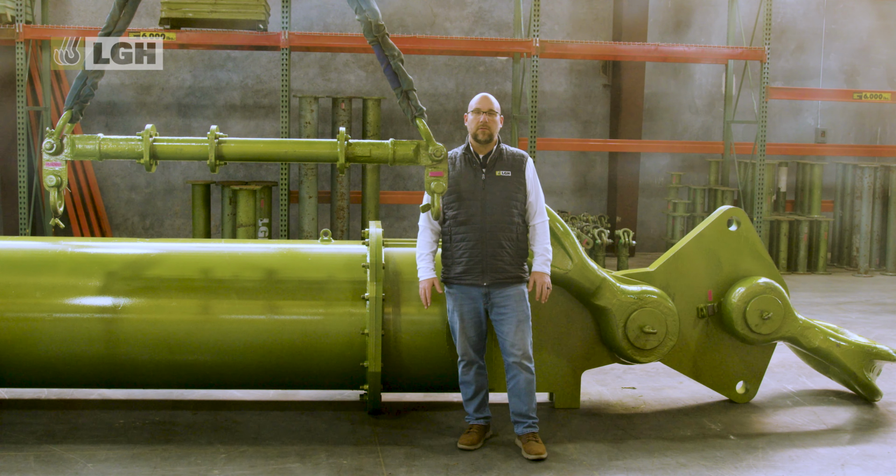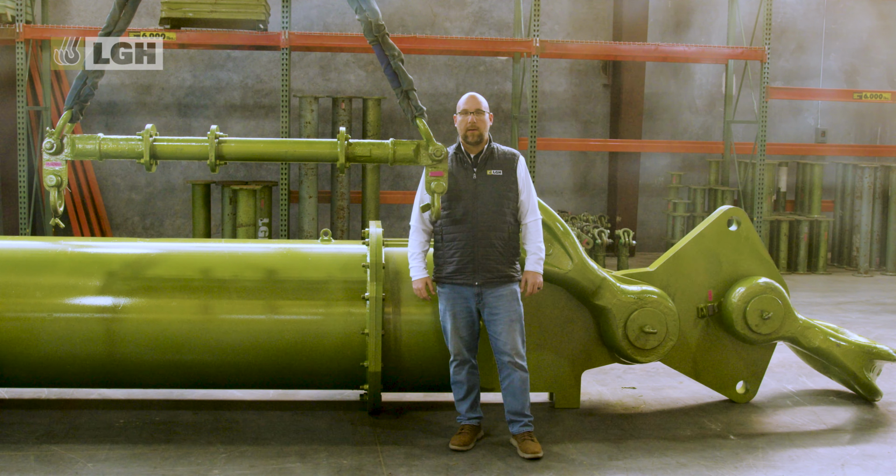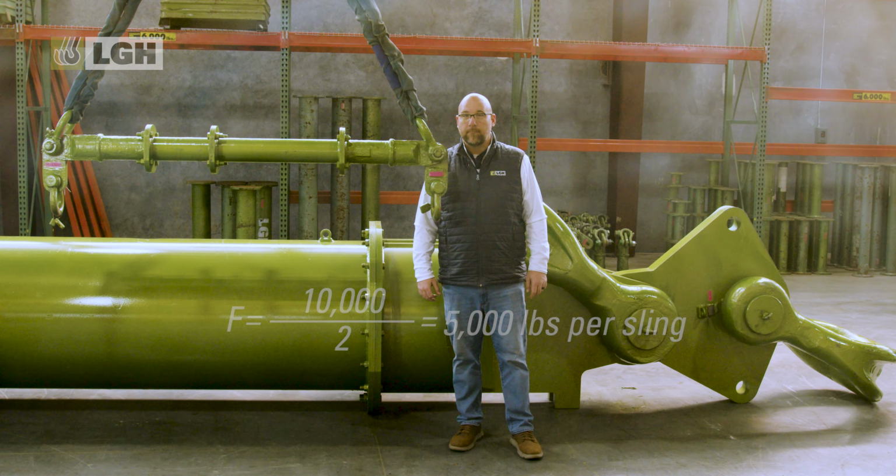To demonstrate, let's say we are lifting a 10,000-pound load using a Modulift spreader beam with 2 slings at a 60-degree angle. Basic force distribution without sling angle effects: the load is split equally between the 2 slings. F equals 10,000 divided by 2, which would equal 5,000 pounds per sling.